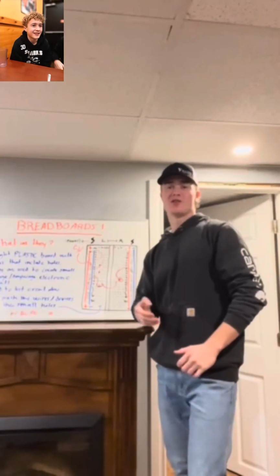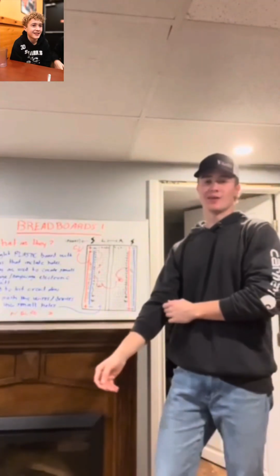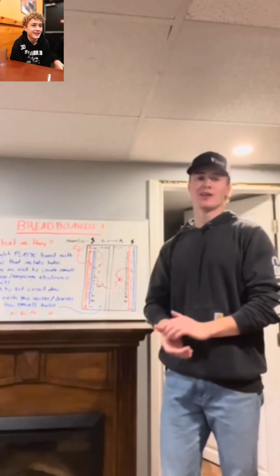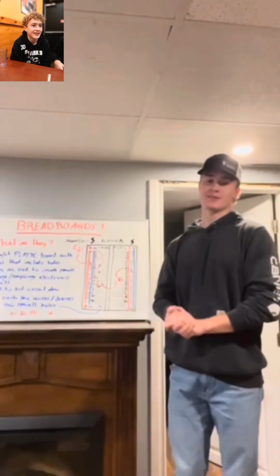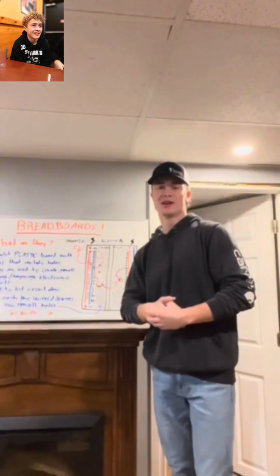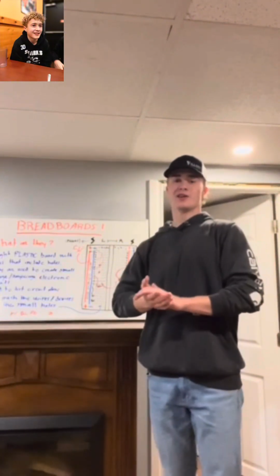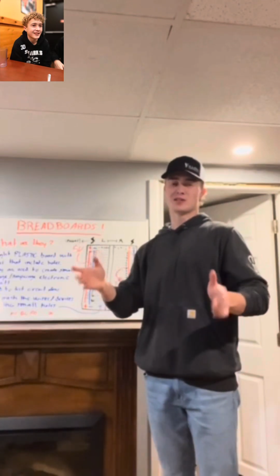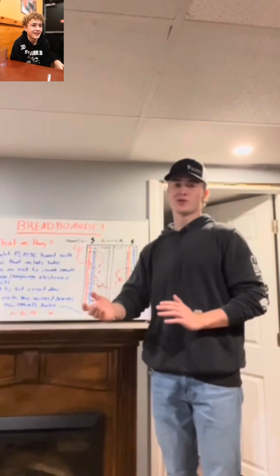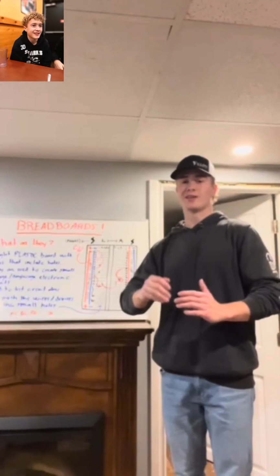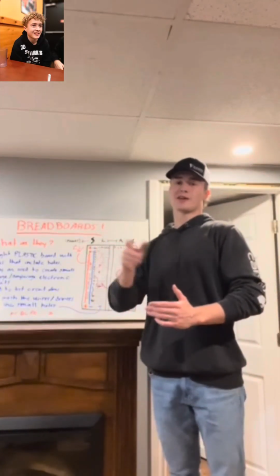Alright, now we're going to get into the why. Like I just mentioned, number one, it's to limit or control the amount of current we have within our electrical system or circuit. Number two, we would use it for voltage dividing or voltage drop. So let's just say I have different electrical components within my circuit that require different amounts of voltage. We would use a properly rated resistor to get a desired voltage drop to that component.